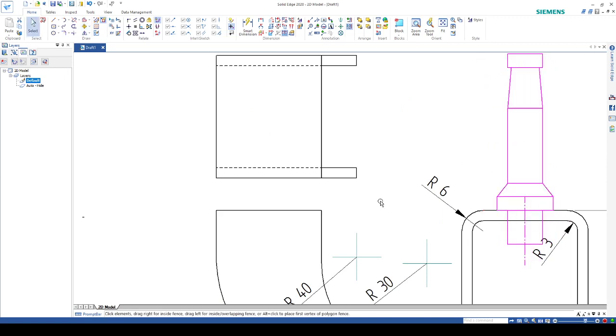You'll notice, however, the drawing says it's riveted in after assembly to an offset of 4 mm. So let's just get the offset tool, 4 mm, with a round of 4.